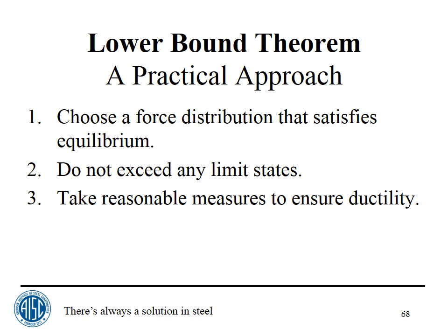Using the lower bound theorem, a practical approach is really to choose a force distribution that satisfies equilibrium. We call that, in this seminar, an admissible internal force distribution. And your computer program, GT Strudel, will produce an admissible internal force distribution for your structure. Do not exceed any limit states, and take reasonable measures to ensure ductility.